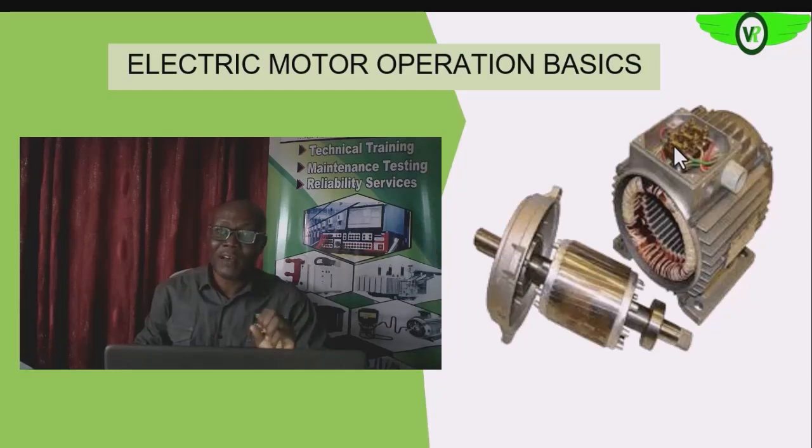So on the terminal block, we have 6 lead outs or 6 terminals, 2 from each of these phase belts. On the terminal here, we can either star the motor or delta the motor, as we have discussed in some of our other trainings. You can check out our earlier training on electric motor testing, or the use of a digital multimeter in testing electric motors. So that is the stator.